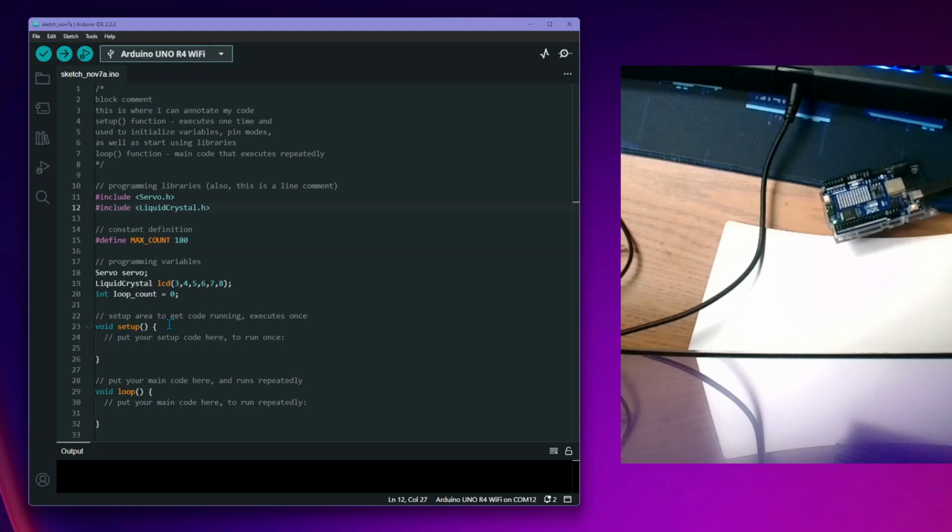So now what we're going to do is fill this in with some actual code that's going to run here. So in this void setup, we'll do Serial.begin, and we can do a tab, and then we're going to do it at 9600 baud rate, and we'll give that a semicolon. Then we're going to do a Serial.println, and say this is setup code, and that's cool. We're good there.